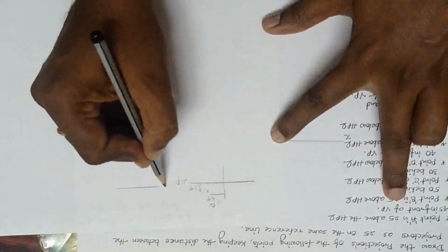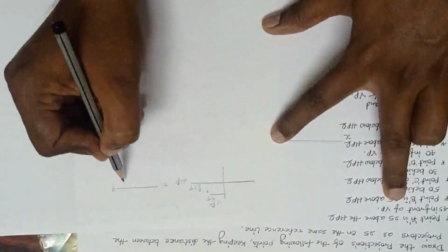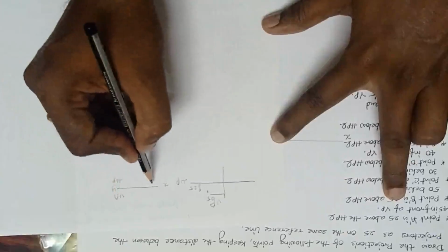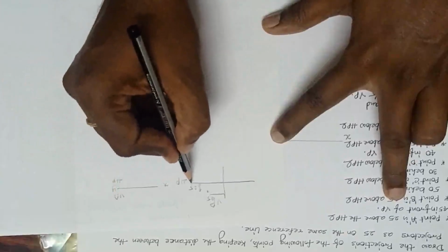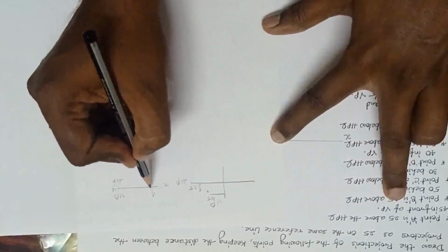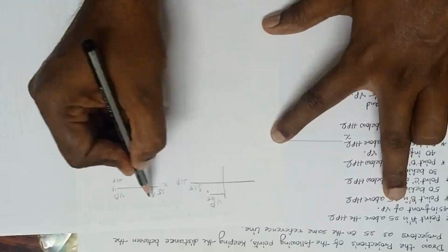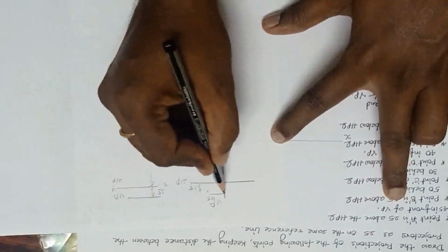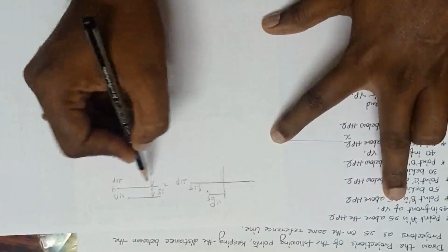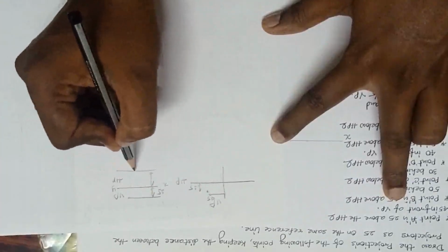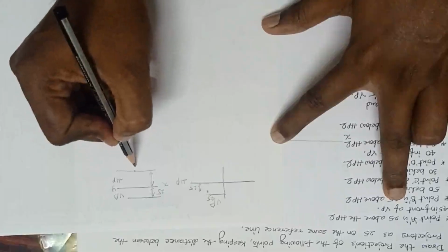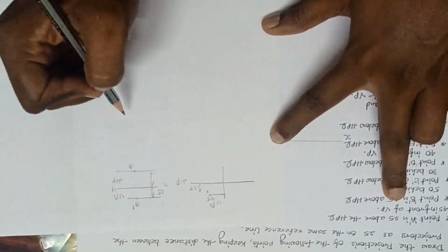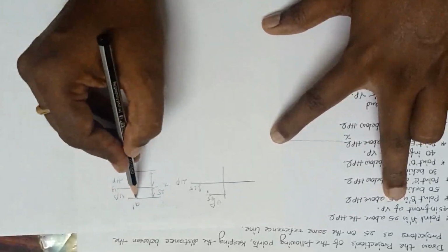So I will draw like this, XY. According to the first quadrant, HP is below and VP is above. I have to draw like this. Distance from HP, it will fall on VP. This is 25. I will draw like this, and 45, the distance from VP. I will draw in the HP like this. I will show the point A here, A, and here also A. Put the dash here, on the VP.